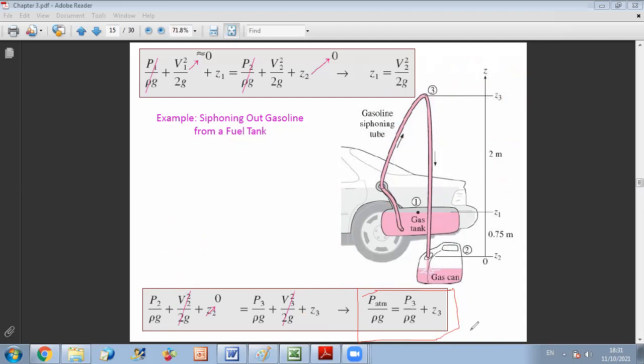So as you can see, the pressure at point 3 is smaller than the atmospheric pressure. And I should pay attention: I cannot go below a certain level, because if I drop below the cavitation pressure, I will have formation of bubbles. Any question on this?